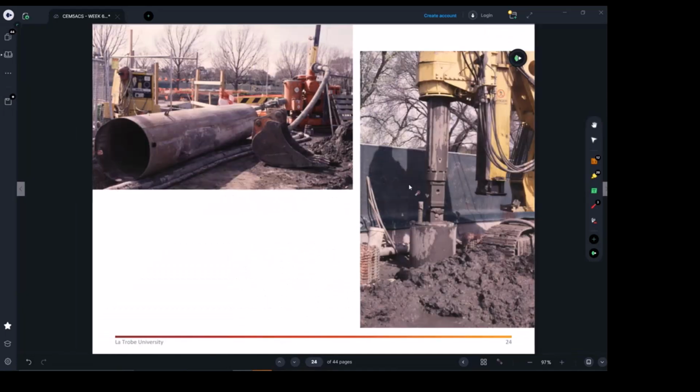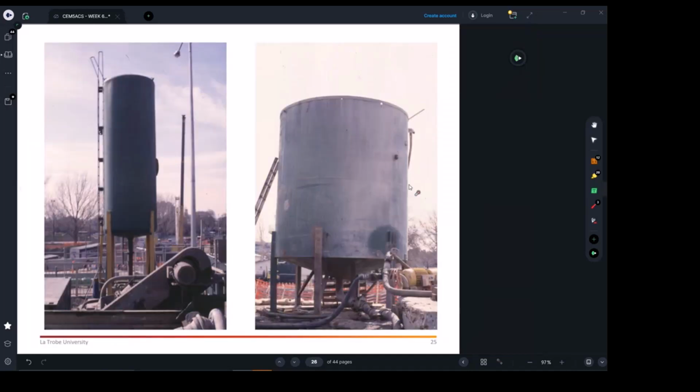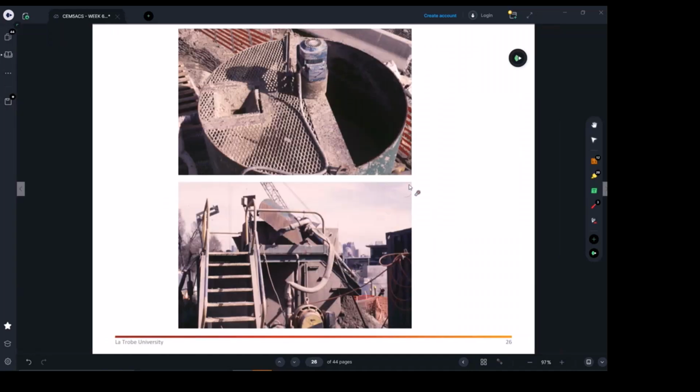It's going to maintain the bentonite pressure to make sure it keeps the water table out of the hole, and also keeps any saturated sand material out of the hole. Right. That's the tanks, which definitely have a cleaning facility and filtering facility.